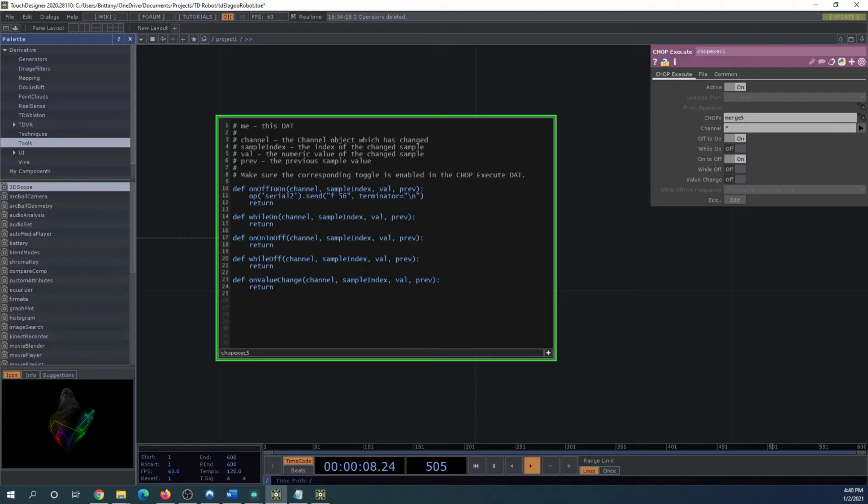Now to send a forward character, and then our speed, which is 56, which I'm pretty sure is too low for the car to actually move. I think it needs to be up to 100. If you guys are having trouble with that, I think it's just because your speed's not high enough. You'll hear it whirring and it won't be moving. So just put it up to 100.